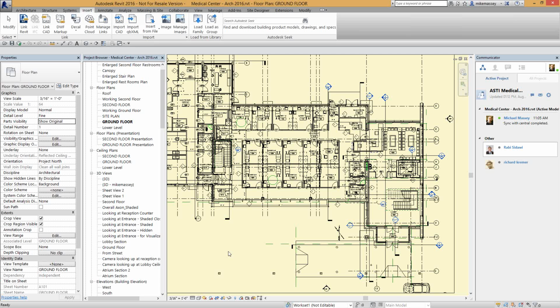The other solution, the temporary solution, would be to create a Revit file and link in those AutoCAD files into that Revit file, and then put that Revit file out onto the cloud and have that Revit file linked into your central file. So basically create a dummy file that those AutoCAD files are linked into, and then you link in the Revit file. Neither one is a perfect situation, but hopefully one of these days they'll add the ability to bring in AutoCAD files straight from the cloud, but currently you cannot.